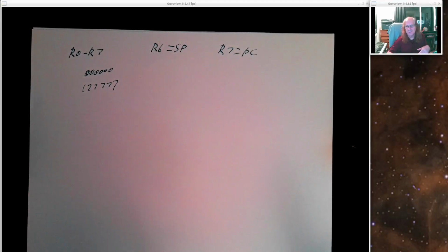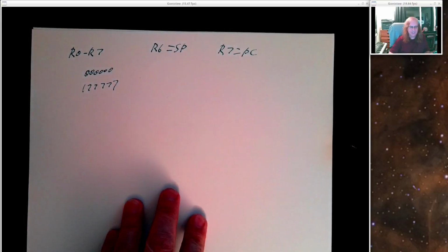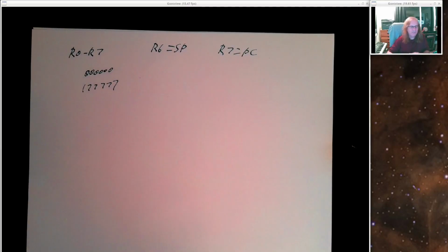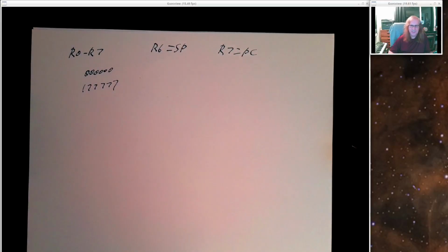So there's a Unibus and there's a Massbus and some other things, and some of these addresses will actually be registers on what would be physical devices. We'll deal with that in another video when we talk about working with paper tape punch and reader, floppy disk controller, things like that. And we'll just have certain registers we talk to interact with these devices. But mostly we just think of it as a 16-bit address bus, and so addresses from 0 through 65,535.